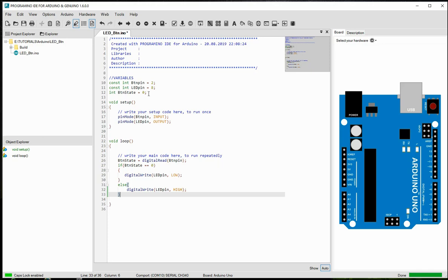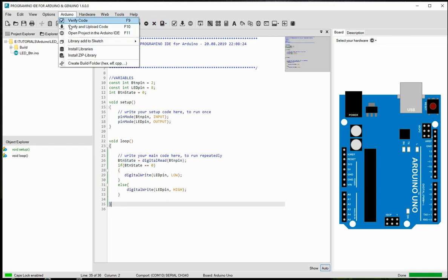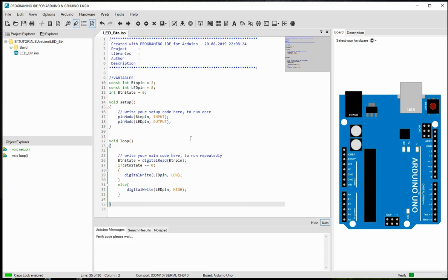So basically at start, we already initialize the state here to 0. That means the LED will be at 0 even without us doing anything. So basically that's it. So we're going to verify or create the build for the X. So it's going to build it and compile to see if there is any error. At the same time, it's going to create the hex file for us.